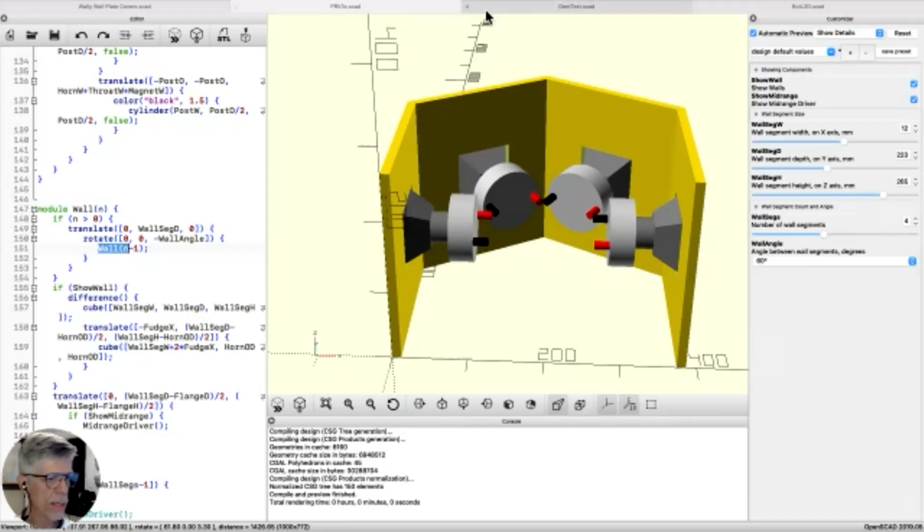Okay. Any questions on that before I go on to the next OpenSCAD? Okay, Bob, the variables, can you do that with local variables or? Well, there really aren't variable scopes the way you'd think in OpenSCAD, because variables aren't like, it's kind of surprising, Scott, how long I used OpenSCAD assuming that variables were just like variables in any programming language, and I could change them, but they aren't that way.